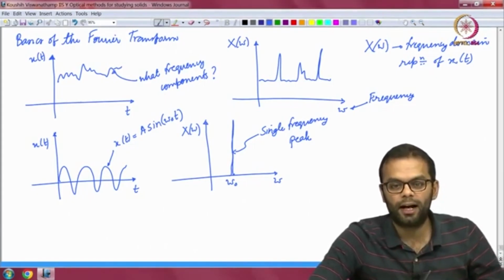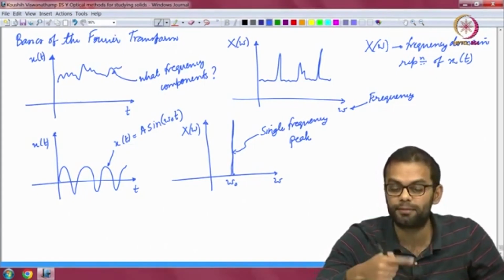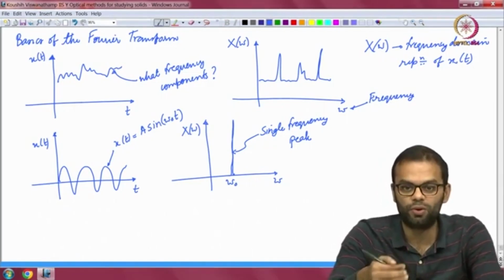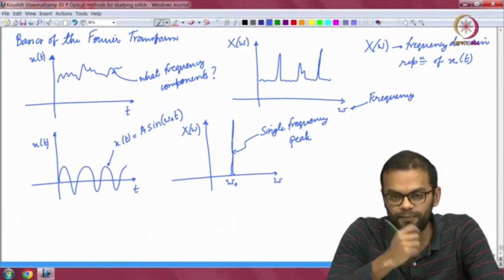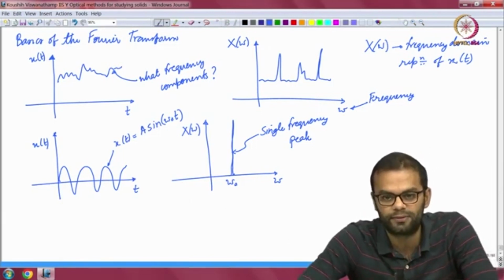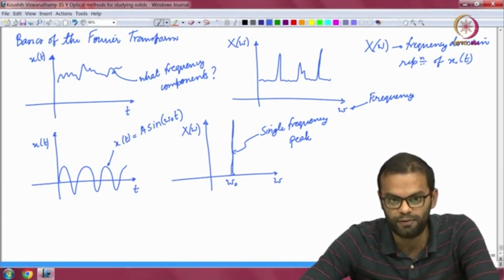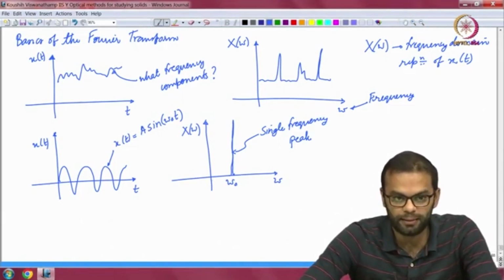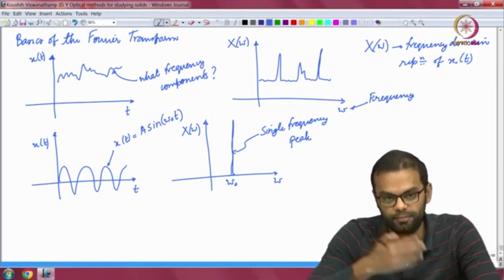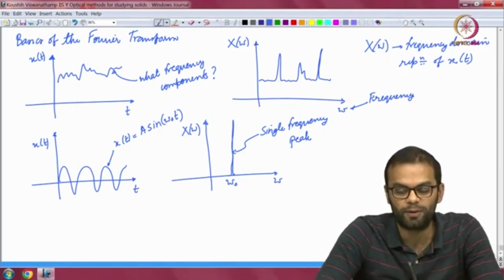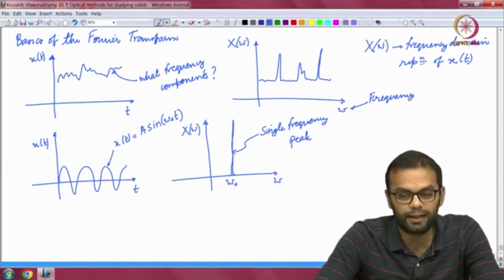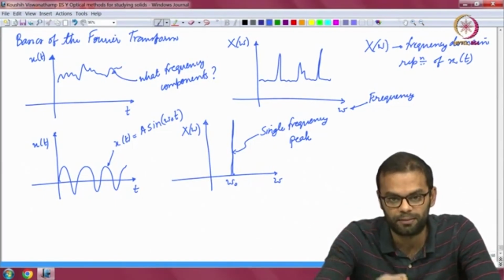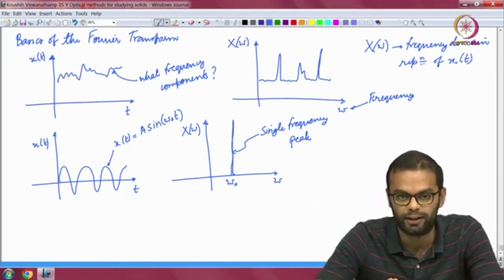So the Fourier transform basically is giving you the frequency information that is contained in the signal, and this type of information becomes very useful. One of the reasons it is very useful is because it allows you to evaluate what are called convolutions. Again, we discussed this in the context of digital image correlation, but I will briefly mention it again, where convolutions are basically integrals of a signal along t, whatever t is, it could be a spatial variable also, and the corresponding representation in the Fourier space becomes a multiplication, just a product, right. So it is easier to evaluate.